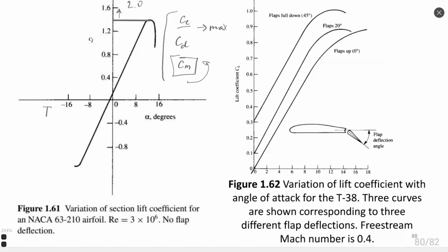These three parameters are just from aerodynamics, but when you design a real structure, you need to consider structural strength, dynamic characteristics and the others. Storage, for example: if this airplane uses liquid fuel, you have to put a tank in the wing, so it must have sufficient volume and sufficient structure. And there are many other questions. Okay, just from the aerodynamic point of view, you need to see these parameters as I showed you on this slide: lift to drag ratio and values of momentum coefficient.